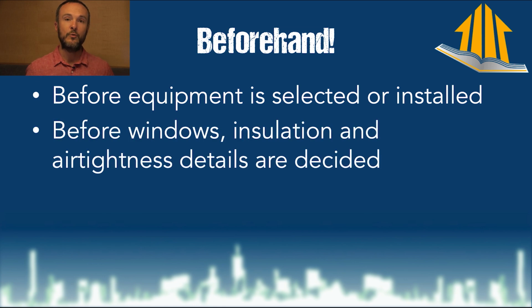So you want to make sure that you do it before the windows and the insulation and the air tightness details are all decided, because you can now make decisions about that stuff. You could say, well, for example, TinyLab, I have a small heat load, and you're going to see that in a little bit. I could insulate this place better, but why would I do that? Because I still have to select the same exact equipment. I'm dealing with drops in the bucket at that point.